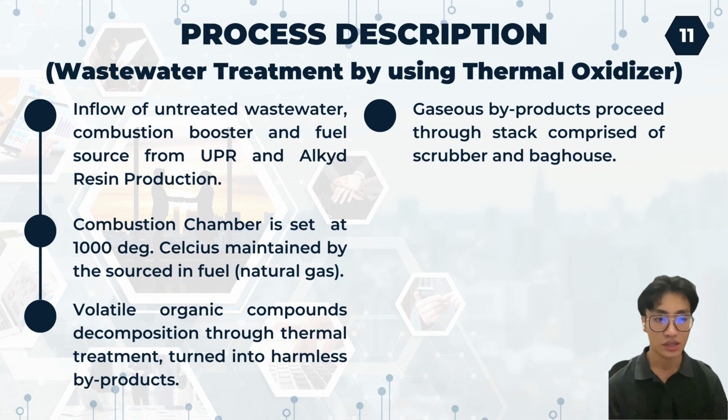So in the combustion chamber, the organic compounds are thermally decomposed and get turned into harmless byproducts, which are carbon dioxide and water vapor. The waste stream will usually be retained within the chamber for a sufficient amount of time, typically around 0.5 to 2 seconds, ensuring the complete oxidation and destruction of volatile organic compounds and hazardous air pollutants.